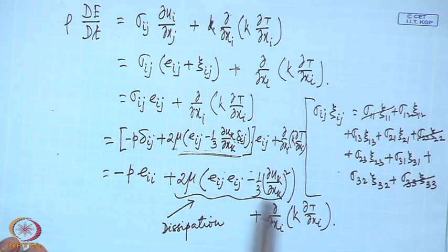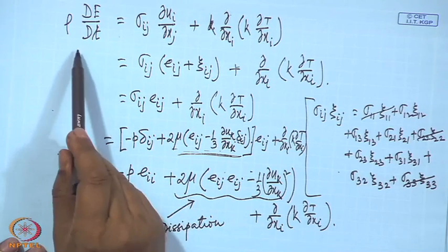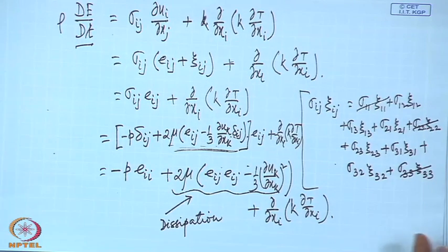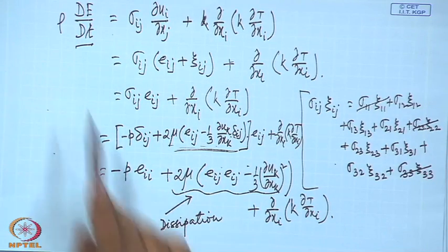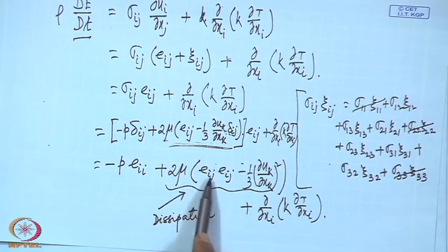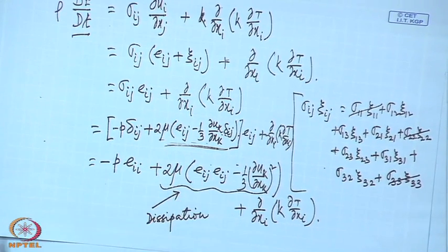So, the equations can be solved separately, and once that solution is found, particularly the velocity field, because to solve this equation you must know the velocity. This equation contains velocity, even in the E term. When you write this in the full expanded form, there is velocity associated with it. So, without knowing the velocity, this equation cannot be solved, but the other equations can be solved without knowing the temperature.